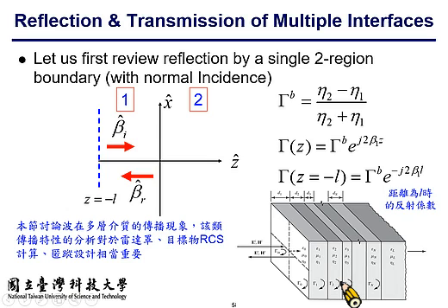You simply adjust the phase variation back toward your observation plane. The blue dashed line is your observation position. So you translate the reflection coefficient from the boundary to your observation plane using this phase change relationship. Okay?